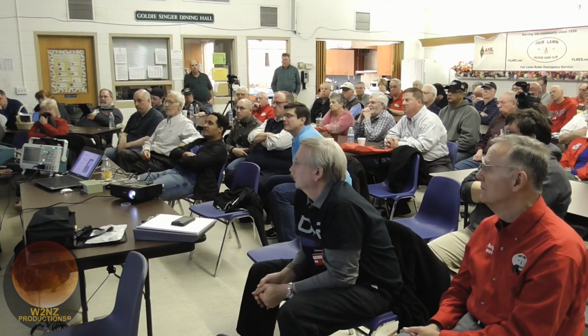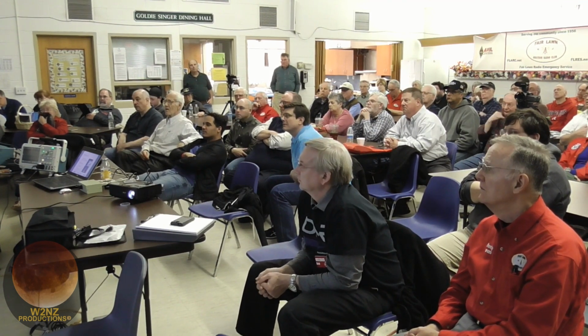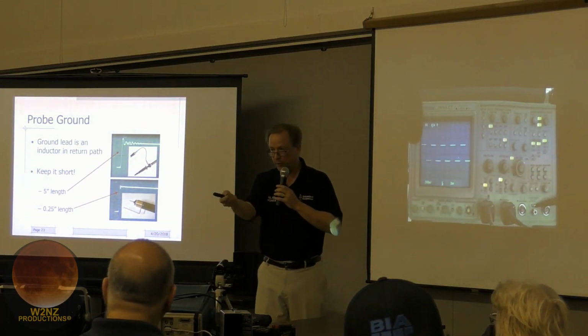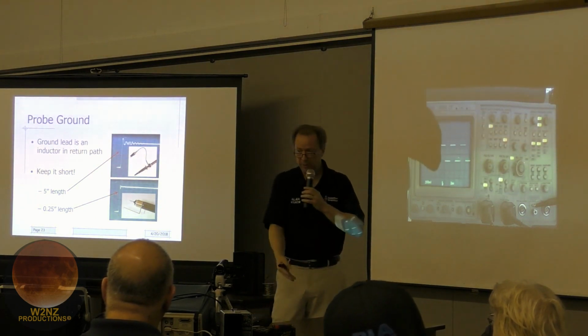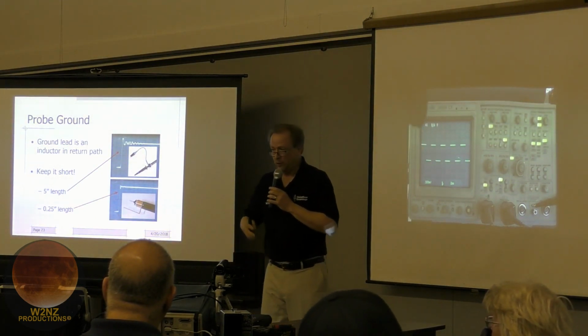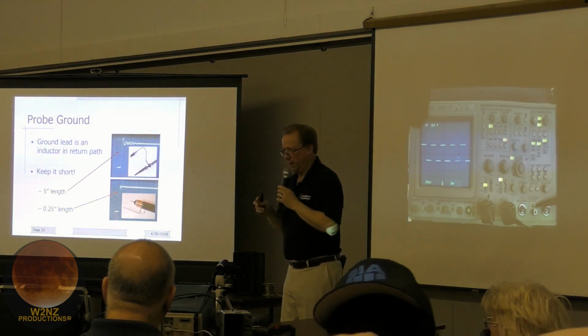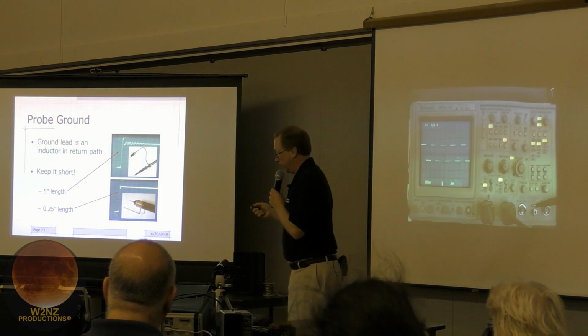Yeah. What if you remove the ground lead? If you remove the ground lead, then the ground will either be capacitively coupled through the air or go through the ground of the scope's plug. You've got earth, you've got a power supply that's powering your circuit, it's grounded. You'll always get that image current coming back somewhere, but the worse you make that return path, the more you can affect things.